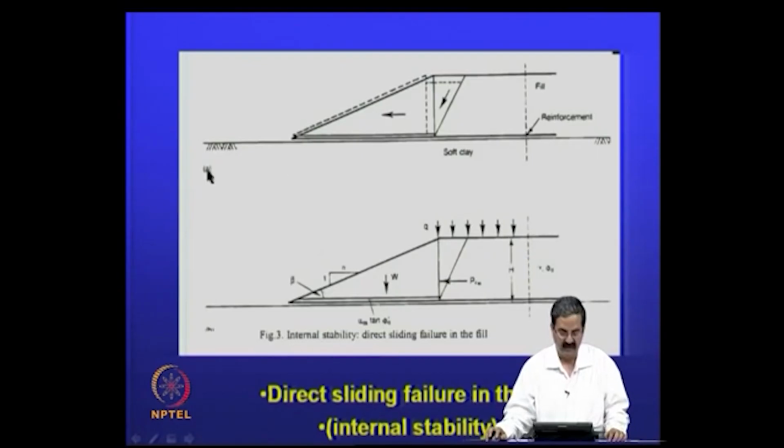nH. If n is the slope and h is the height of the embankment, I said 4 meters. So, if I want to express it as 1 is to 2, I should say n equal to 2. So, n becomes 2, so 2h will be the horizontal extent of the slope. So, this is 1, this is 2. So, this n is also important.